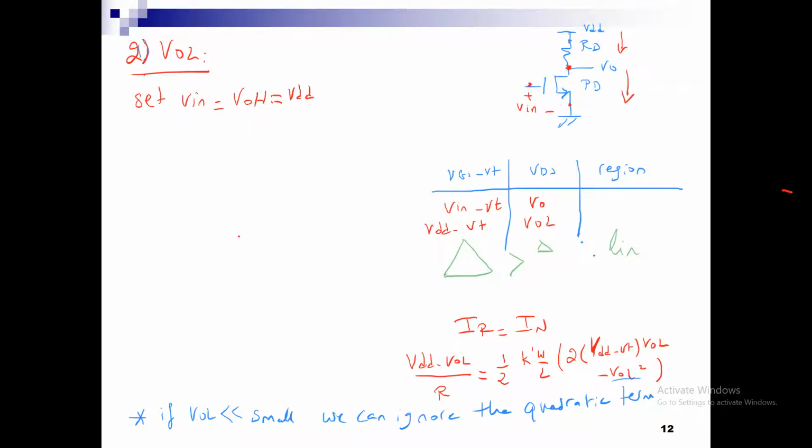How do they behave when they're unloaded? I mean, there is nothing on the VO. Okay, when we study the VTC characteristics of the inverter, for our purposes we are only going to study the transistors, the pull-up and the pull-down devices. Now assume I have two inverters. How do things happen in real life? Only those two devices. The loading affects me only from a delay perspective.